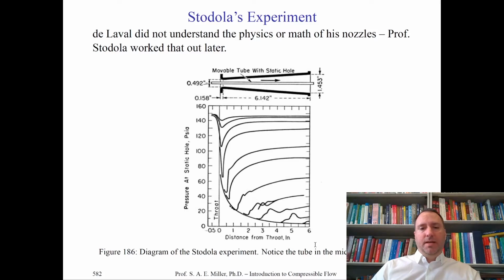Well, you might say that the normal shock, of course, has a small thickness. The pitot static tube also has a larger thickness. The shock wave is not completely stationary, and so it's being smeared out and averaged over a particular distance in the nozzle throat. Also, of course, the theory uses an inviscid theory, and he's dealing with, of course, a viscous fluid, which is air. All these cases contributed to, of course, this measurement problem.